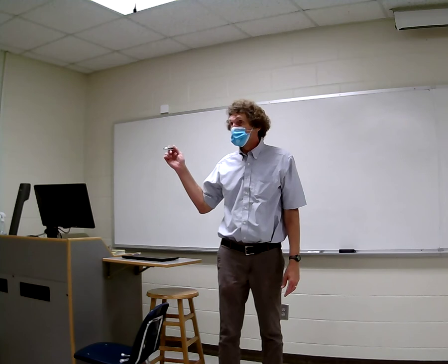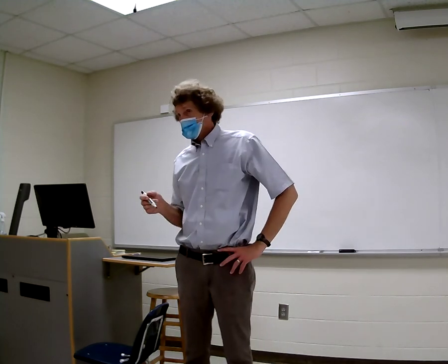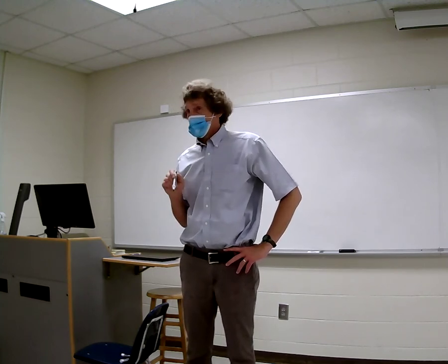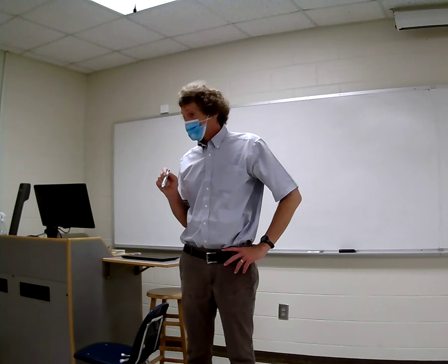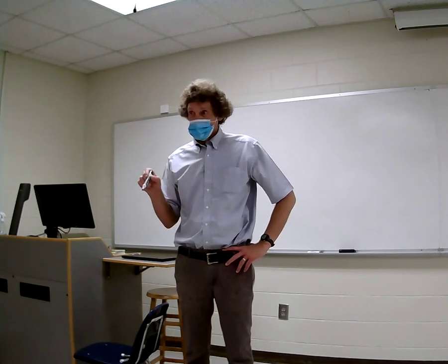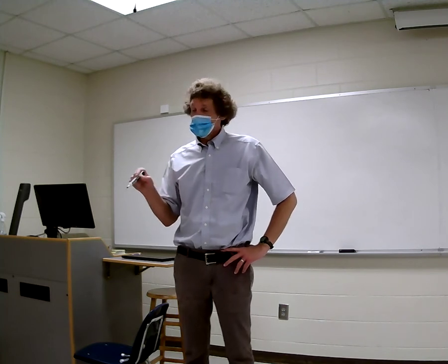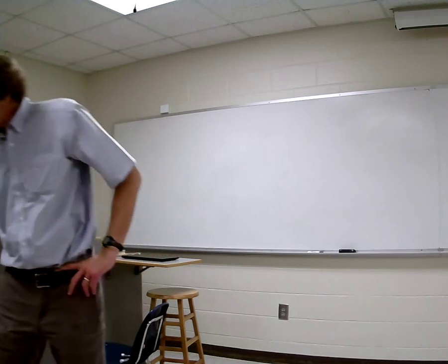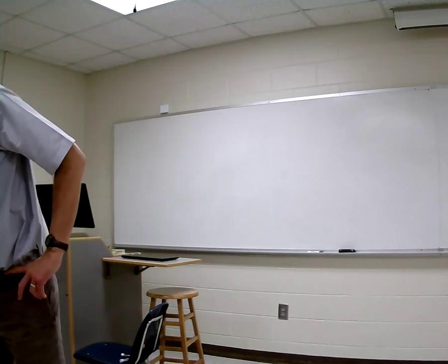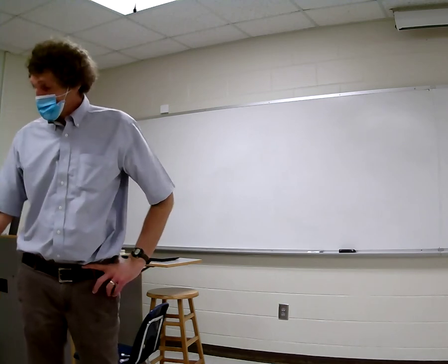Yesterday when we were solving on that Smith chart, I can't figure out where we got one of the values from. How about this? Why don't we do that problem and get your calculators out, and if you have a rotated Smith chart, you don't have a rotated one? You can draw a rotated one with a compass. Put it right in the center of this one, get the radius of the one circle, take it over to the center and do it. But you can redraw that, and you've got a nice Smith chart there too.